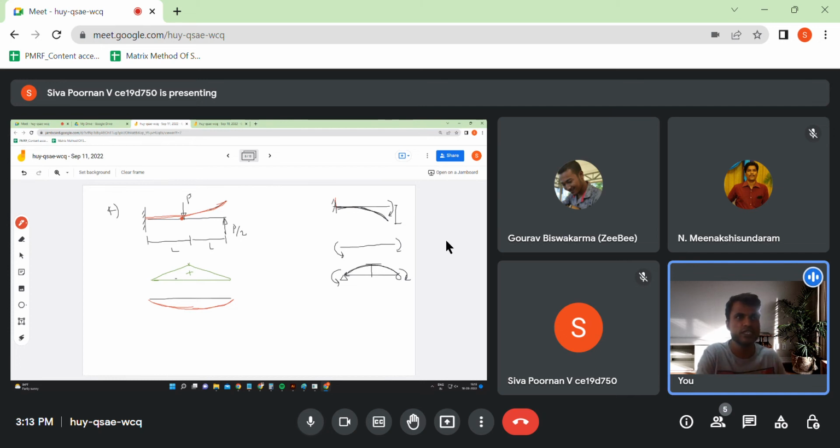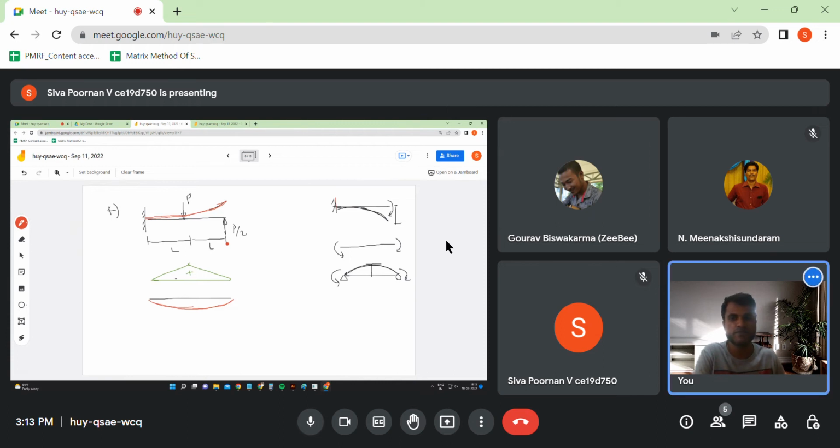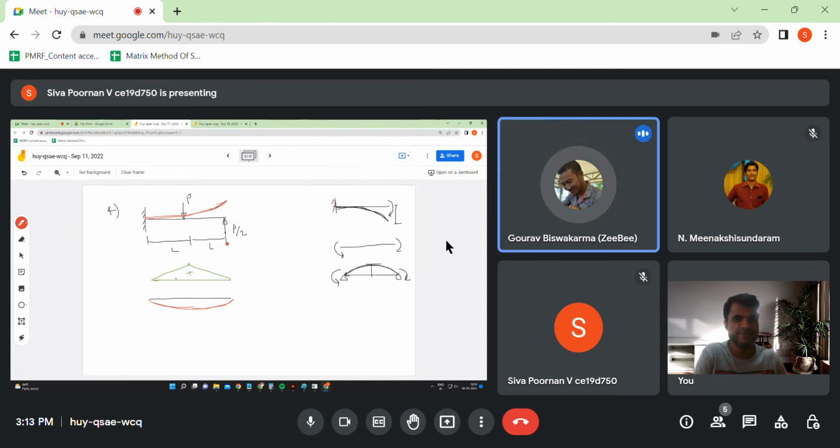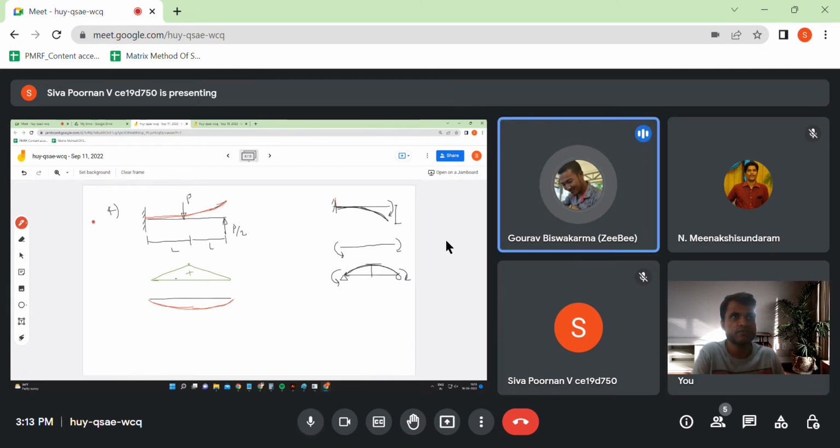Any doubts on that? So where should the deflection be maximum? It has to be at the load point, the midpoint. At the midpoint, because the slope is now zero at the far end. The central deflection should slightly shift towards the right.